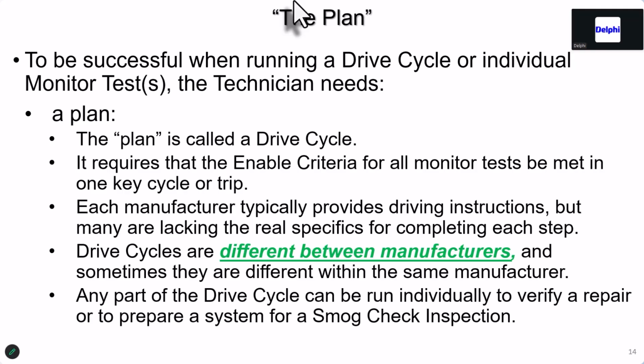You want to work for the PCM. You want to verify or repair. I attune it to the fact that someone says they clean the EGR ports, and I say, how well did you clean them? They say, well, I clean them as well as the boss pays. And then that vehicle comes back because they didn't bother to go out and take a drive and find out that it just barely passed and is probably going to be back within a month or two. So the idea is there's ways to follow up on this, and this is why we're doing it. We want to avoid the comebacks.